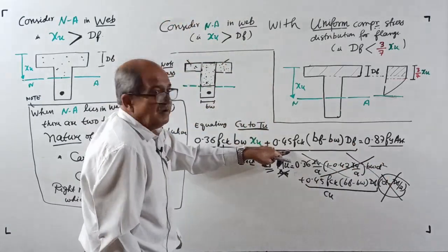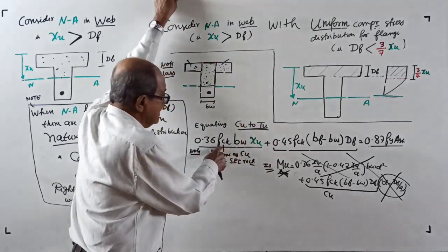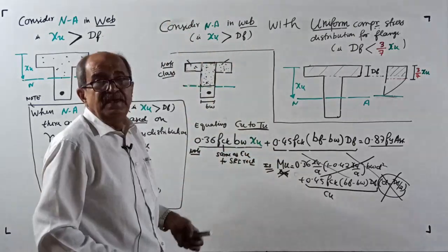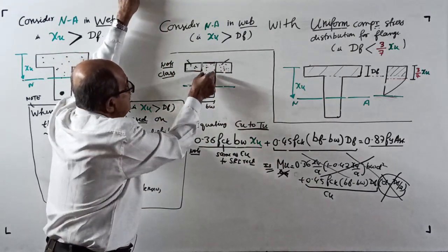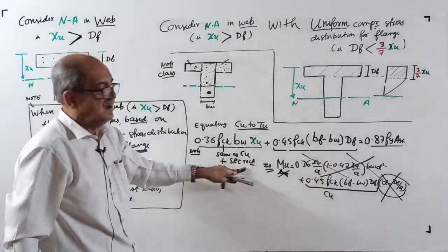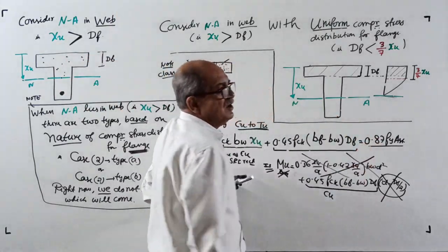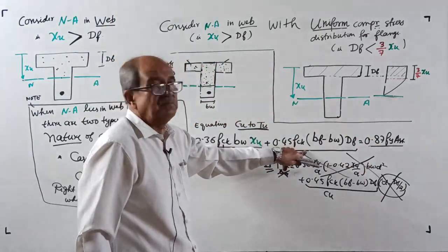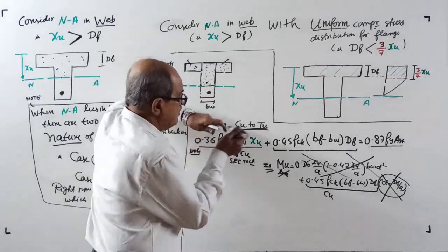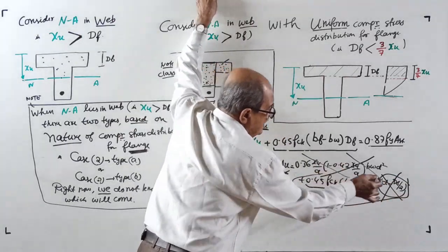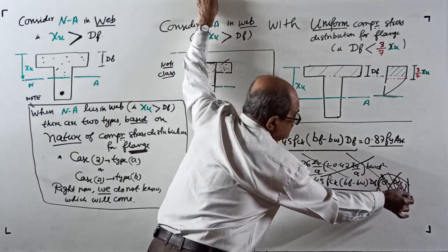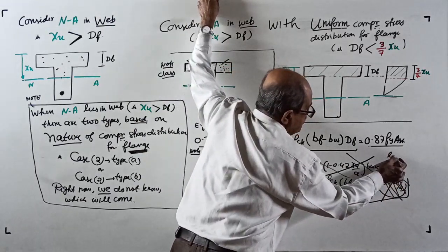The second term, how to remember? Easily: same as a rectangular section of width bw, singly reinforced section, right hand side is the same, 0.87 fy Ast. For the second term, take whatever is the second term in the MR equation given in the IS code, skip that last term, which is actually the lever arm.